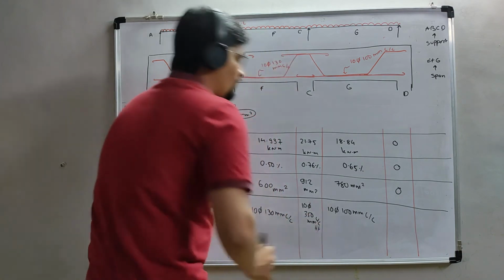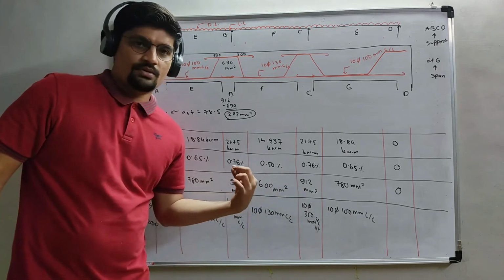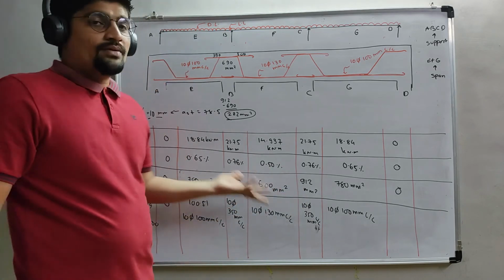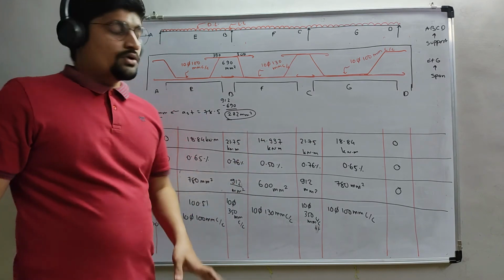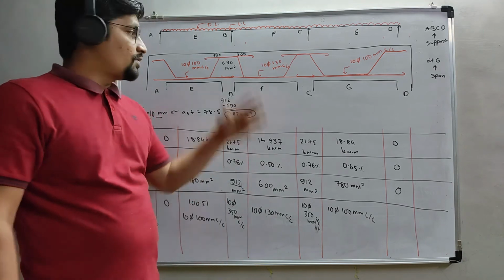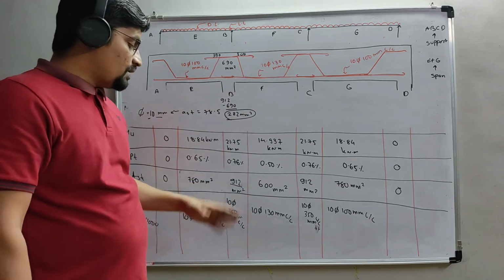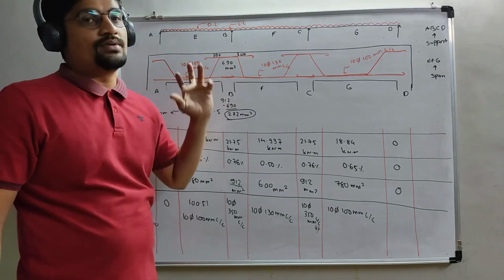Okay, I hope you all understand what we have to do here. We don't need to provide 912 because it will be overweight and the beam will fail, because already we are getting 690 mm square from the midspan to the hogging portion. So why put extra 912? It will become so heavy.